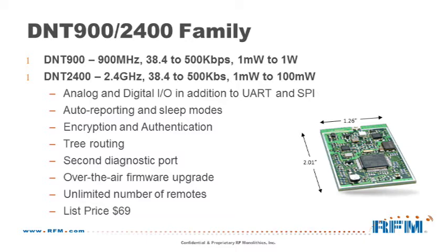There's a second diagnostic port, and this is important because if you have an application where you want to monitor the health of the network, you can do that without that diagnostic information being embedded with the application data. So you just simply have a separate UART where anything that's coming out of that is the diagnostic data. So you can have a diagnostic utility that only does diagnostics, and then your application only deals with the application data. So a very easy and straightforward way to get real-time network health information without complicating the application.